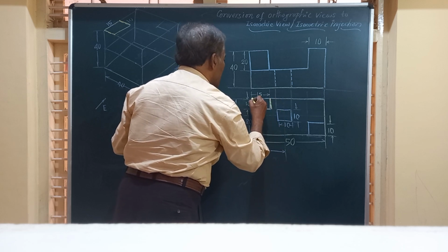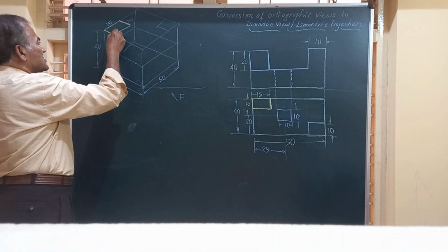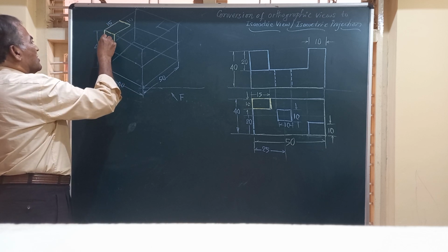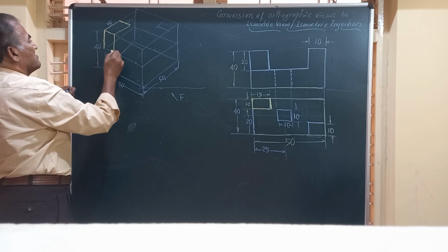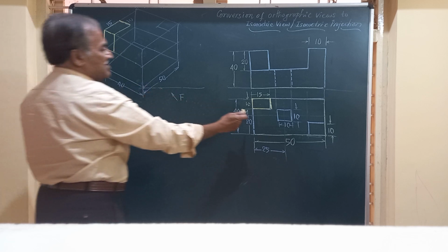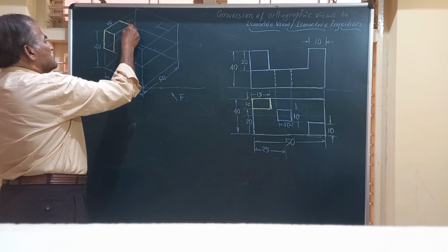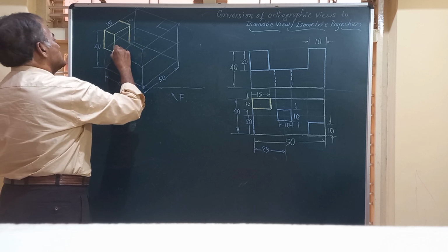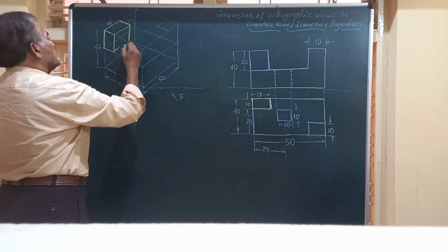So this top part I have completed and it has got a depth of 20 mm. So from all these corners, I am going to draw vertical lines of height equal to how much? 20 mm height. So friends, this is one of this face. This face is this one. And similarly friends, let us project from these other corners and complete the projection on one of these ends.